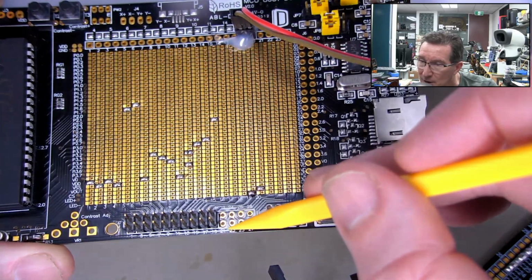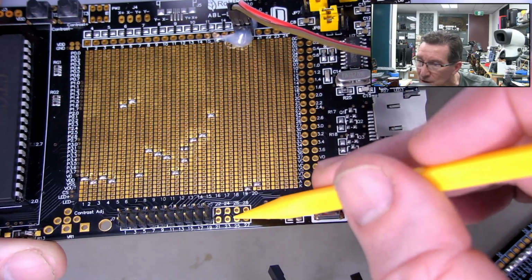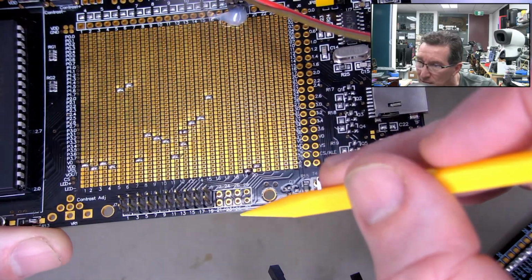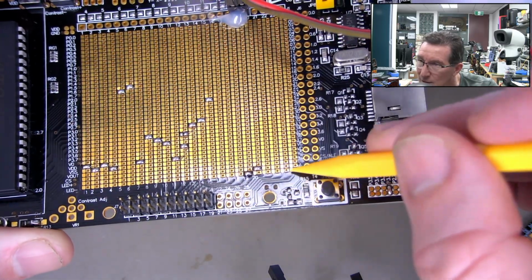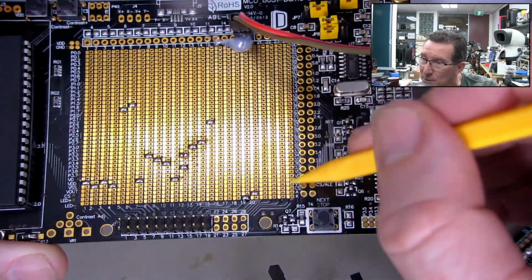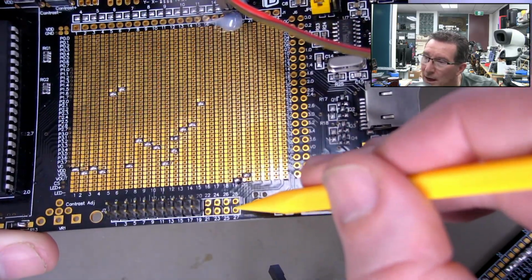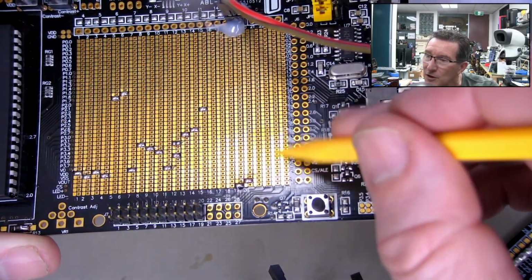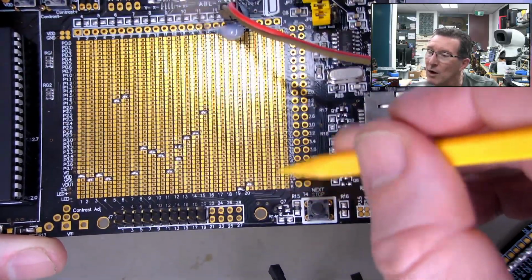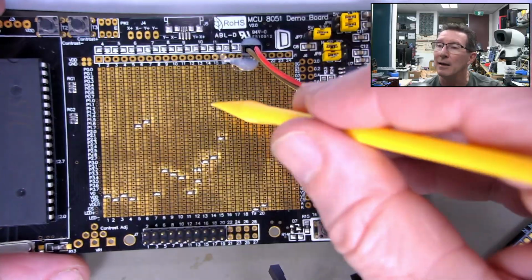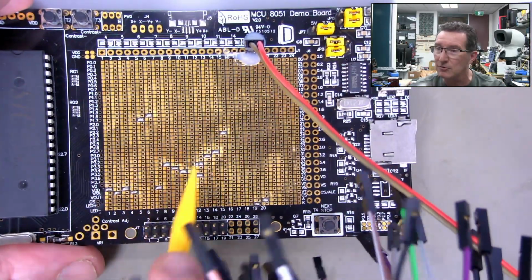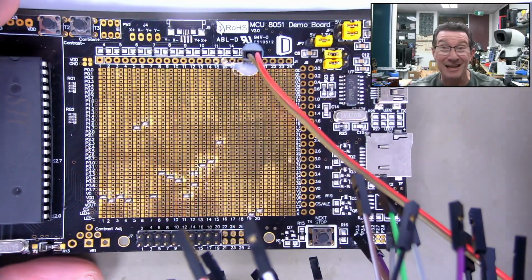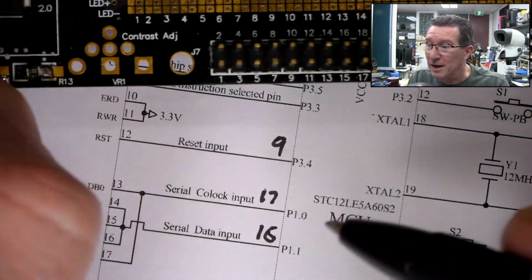24 seems to be going to 2 locations, actually. 24 seems to be bloody black solder mask. It's hard to see, but is that 20? Yeah, 24. Yeah, 24 does bugger off to there. Are they also going to the vertical columns as well? So, anyway, there are a few spare pins there I can use without touching the rest of this matrix, and just leave that intact if I need it. This is actually working out quite well.